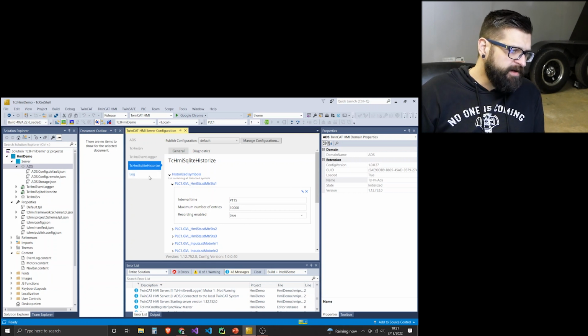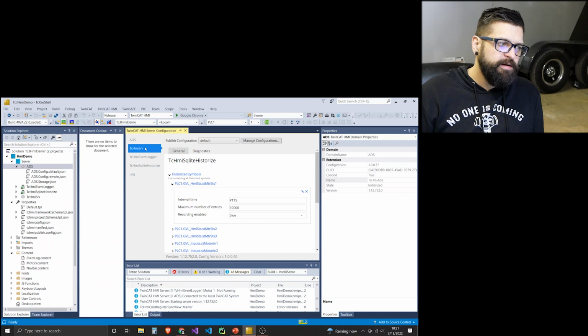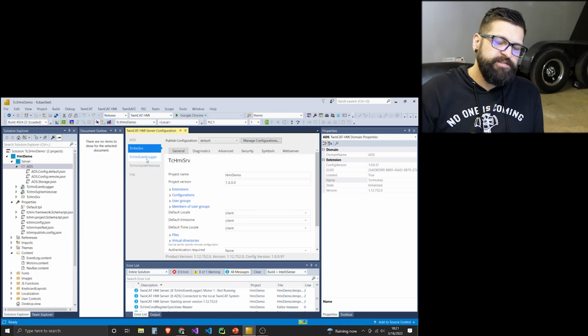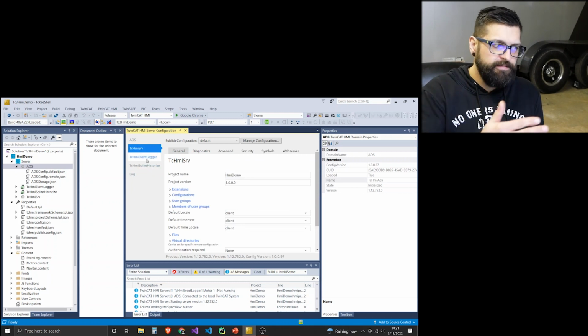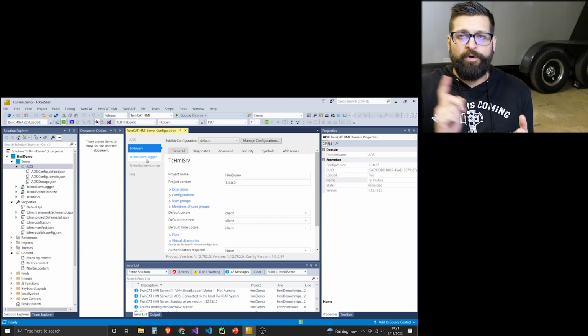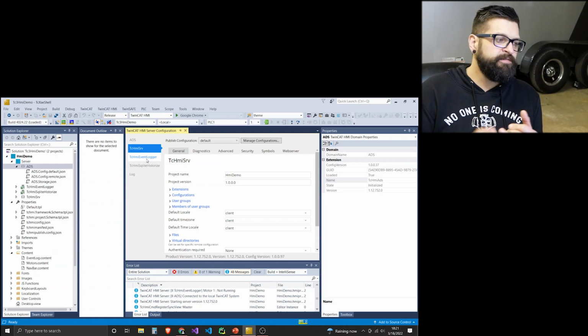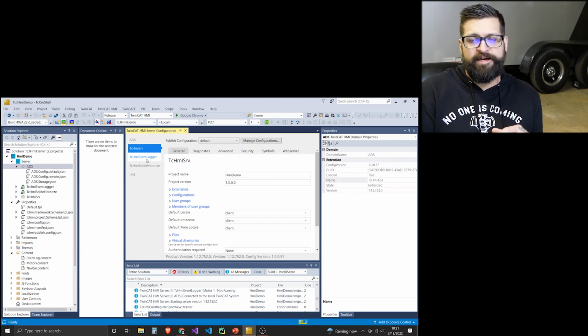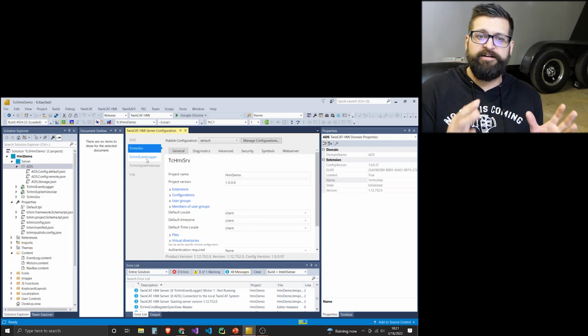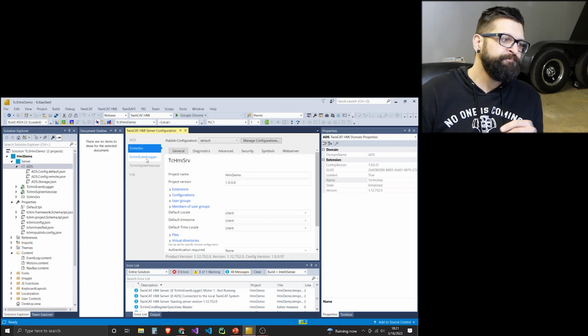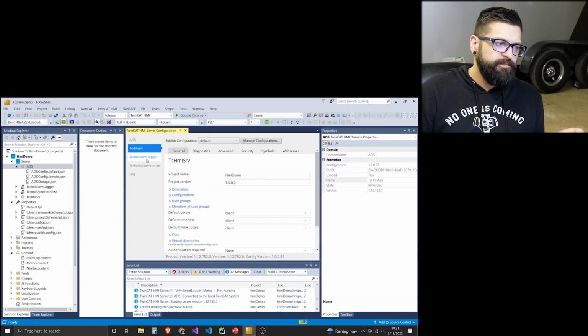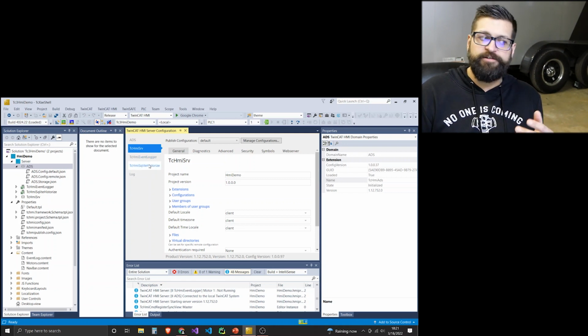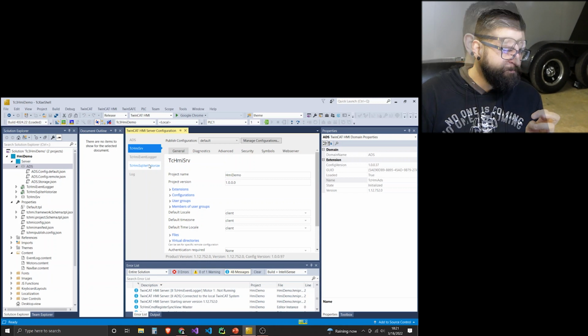Okay, so those are the primary sections that you need to read in the manual and configure to publish a web application that you develop. So for an HMI project, these are the main things that you need to have set up: 1, ADS, to talk to your target system; 2, web server addresses and passwords and all that stuff to actually publish to your web server; and then doing configuration on your extensions for the kind of functionality that you want from those devices.